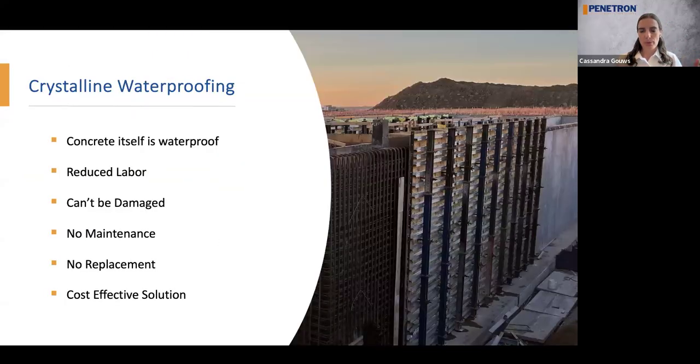The crystalline waterproofing system is completely different. Your traditional surface applied creates an actual barrier, right? Now, the crystalline waterproofing makes the concrete itself waterproof. So there's no more barrier. The concrete itself is waterproof. And because the concrete is waterproof, there's reduced amounts of labor because you're pouring the concrete in any case, and now you're actually placing the waterproofing at the same time.